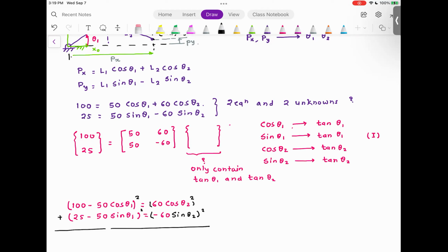But recognize that the expression is going to have only theta 1, which means after you simplify everything, you are going to get tan of theta 1 is equal to some expression. Once again, you are welcome to do this, but I'm not going to do this because this method, in my personal opinion, is too restrictive to certain problems. This method will not work for all problems. You have to use some combination method to solve inverse kinematics problems. And I don't like that.